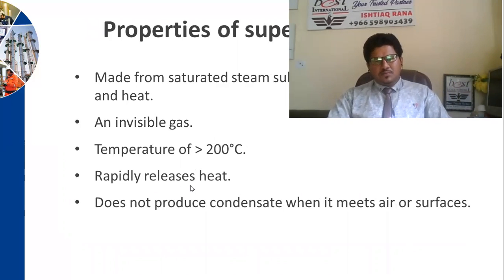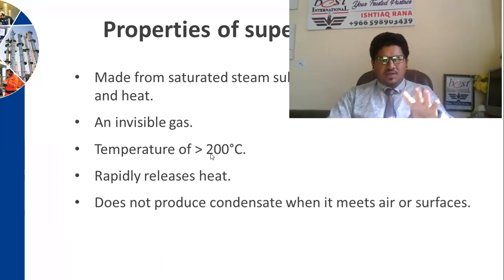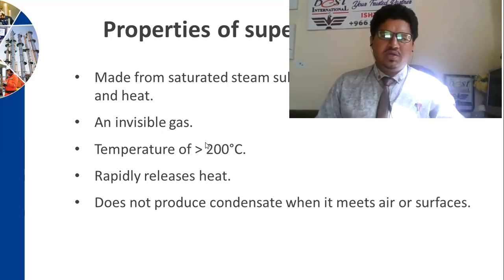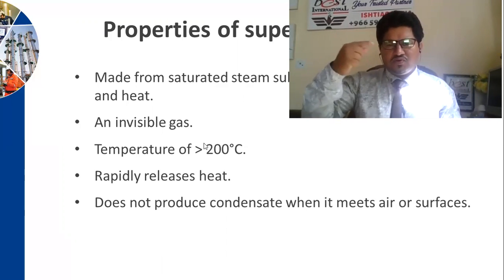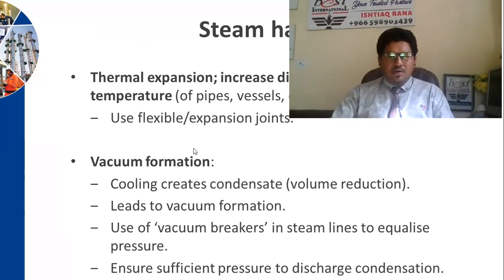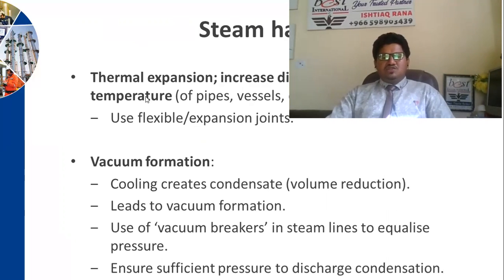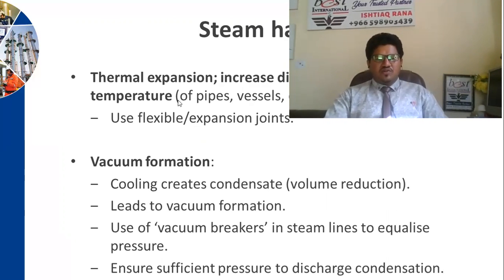It rapidly releases heat and does not produce condensate when it meets air or surfaces. So no water, nothing. It will evaporate everything through heat, but in saturated steam, of course, some humidification will be there. Now, steam hazards: thermal expansion, an increased dimension of the solid by rise of temperature of vessels. Use flexible expansion joints. Vacuum formation: cooling creates condensate, which leads to vacuum, and vacuum breaks it down if the pressure is not sufficient, like